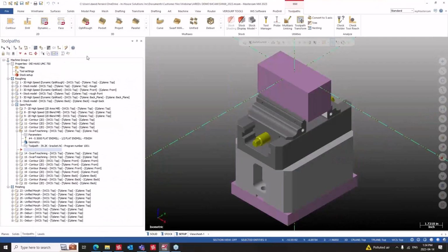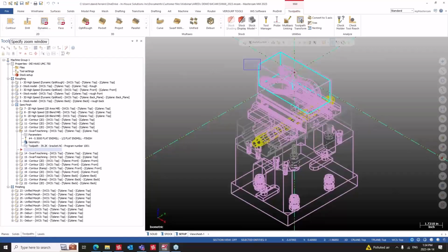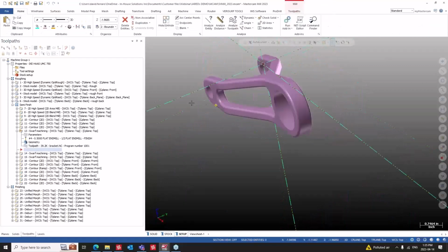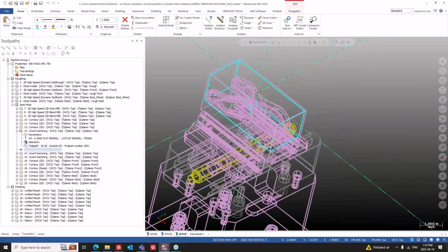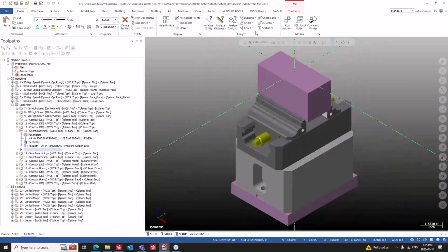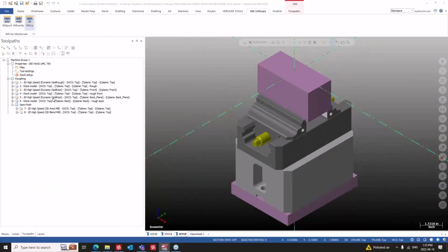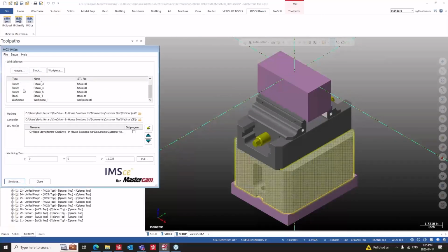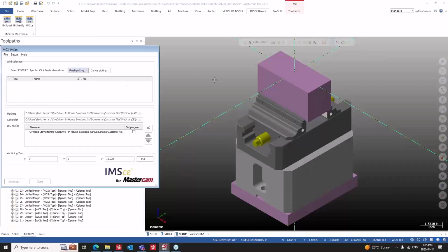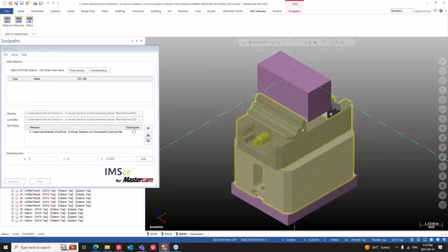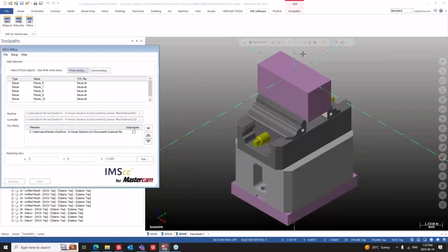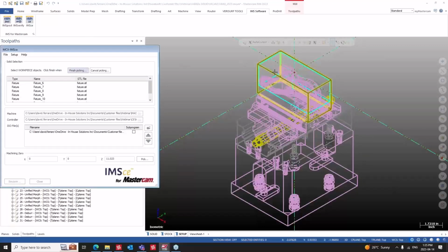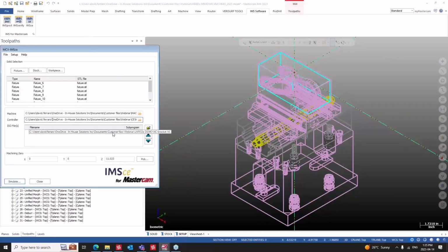So this is an interesting part. It's back on the Haas UMC 750. So nice little part. All 5 axis. So we'll do this, and you can see how easy this is. So in this one here, it's actually saved all the stuff, but I'll just re-pick this. So for fixture, we can screen pick if we want, and then stock and workpiece. And then again, the machine's set, the controller's set, and I've got a NC file. So now we can just go straight into verification.